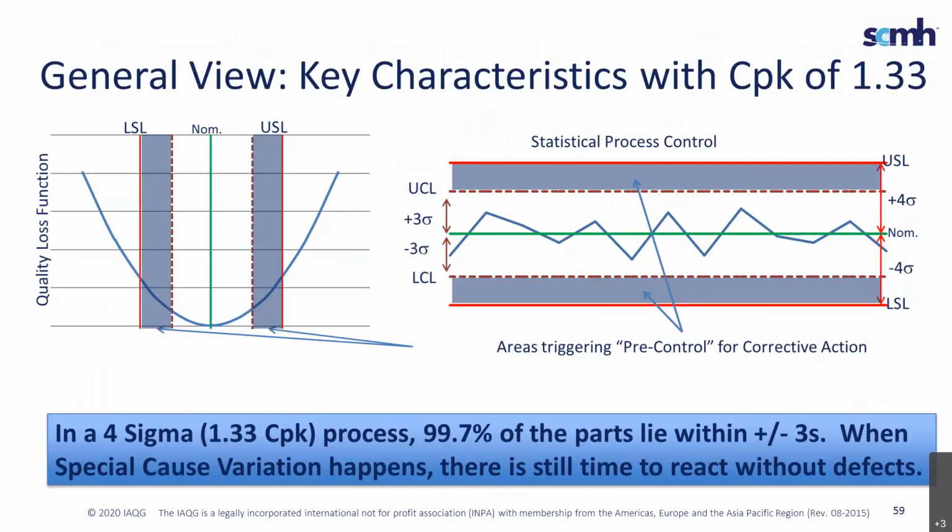Peter talked about this earlier. The reason this is in here again is because this becomes a very important part of our key characteristic control. Key characteristics themselves can no longer be controlled like attribute dimensions, things that are good or bad, things that cross a threshold. They must be variation controlled to reduce variation. That's the whole intent of this.